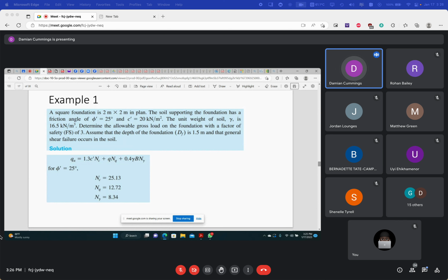All right, there are things that we determine as a practicing engineer. I'm going to be determining the depth that I'm going to place my foundation at, and this is going to be based on my geotechnical data. I'm going to look at my soil profile from my geotechnical report, and determine a suitable layer. And from that, I can determine the depth. And in some cases, there's some guidance from the geotechnical engineer as well.